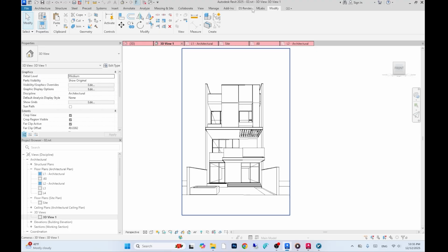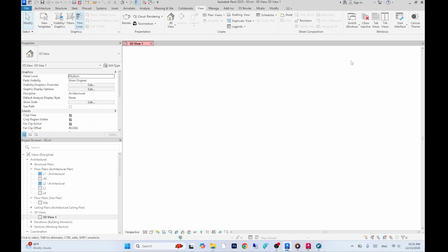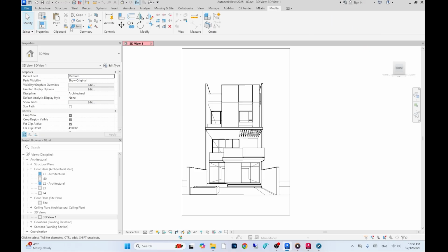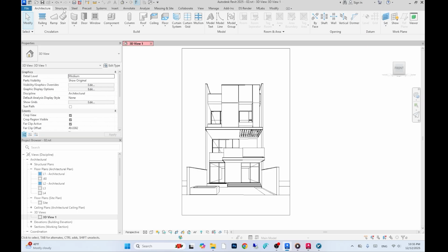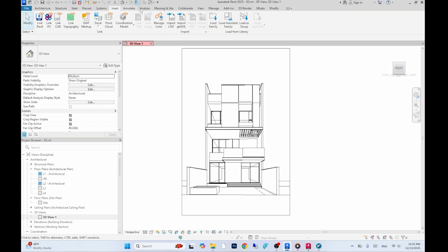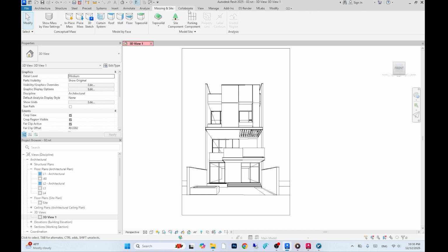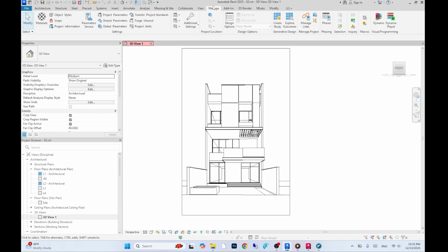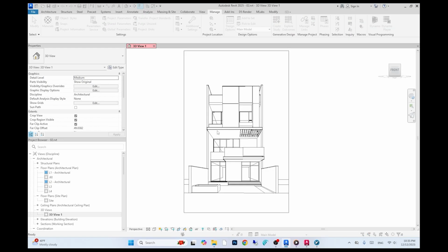To import an architecture project or facade design from Revit into D5 Render, proper material assignment in Revit is required. D5 does not read the objects by their geometry. It only reads the material. This means elements with the same material will be selected together, and different materials can be controlled separately in D5.